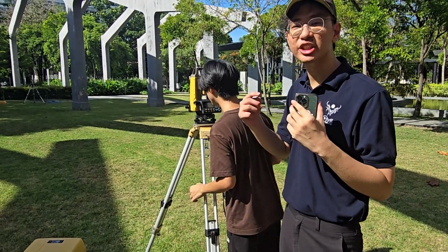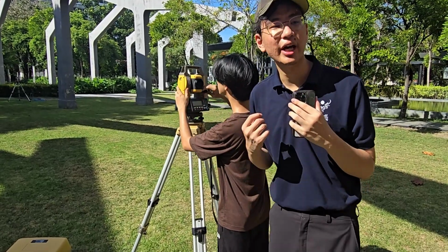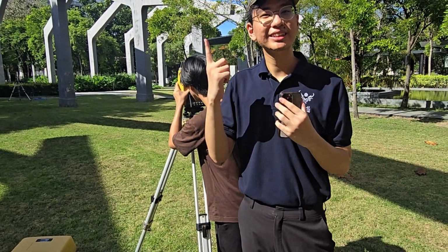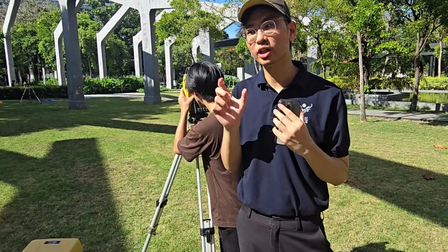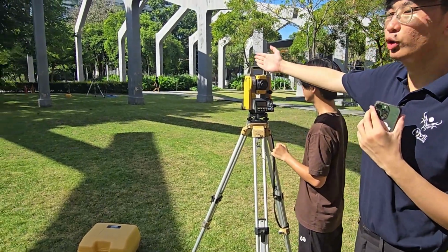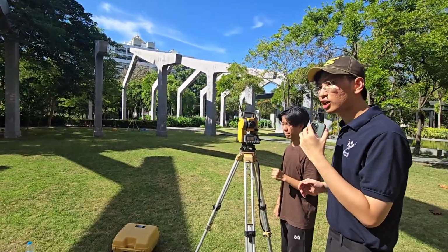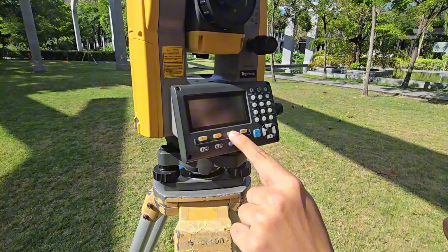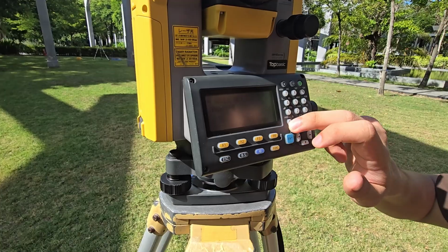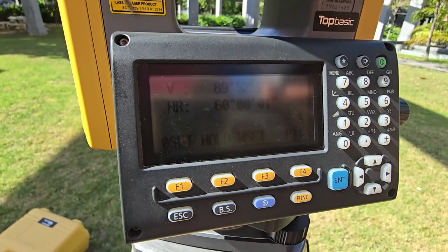In total, for each angle measurement we do in this practice, we will do 3 sets. And each set will start with a different angle value. Because we do 3 sets, we will divide 180 degrees by 3, which gives 0, 60, and 120, a 60 degree interval. So next, we will start with face left as the same and aim at the left target, which is the prism. And then we will set the angle to be 60 degrees. We press F3 to set the horizontal angle, and we type in 60 on the keyboard of the total station, and press return to set the value.